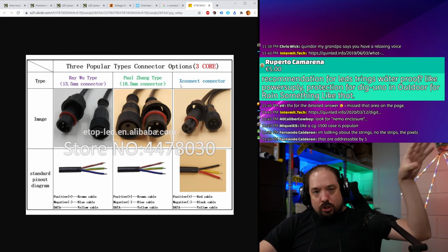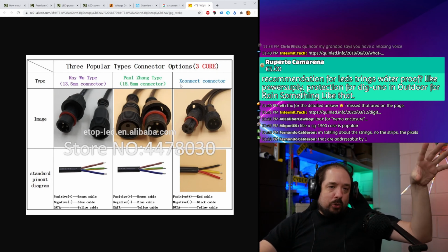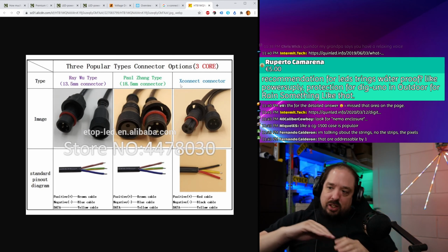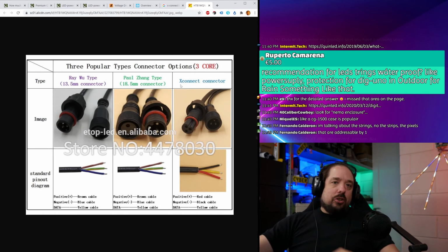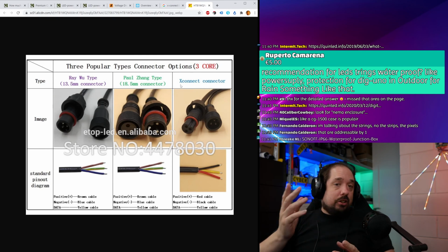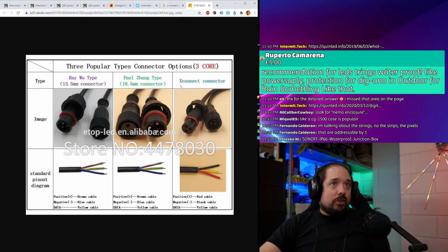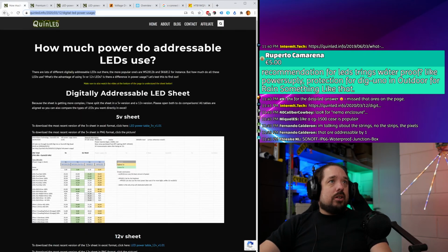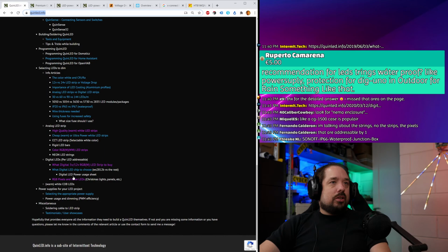So you run an X-Connect cable from the watertight power box through a gland, then to the LED strip, and there you do X-Connect to X-Connect, and then you have a watertight connection there. Then you run IP67 or 68 LED strip. Let me see if I...